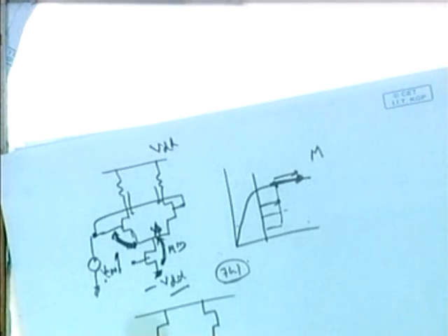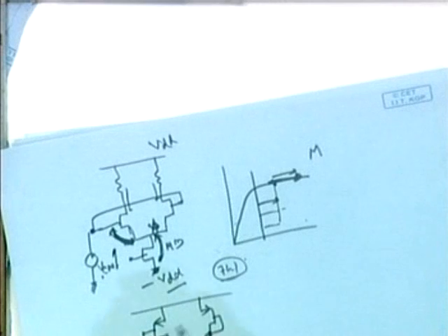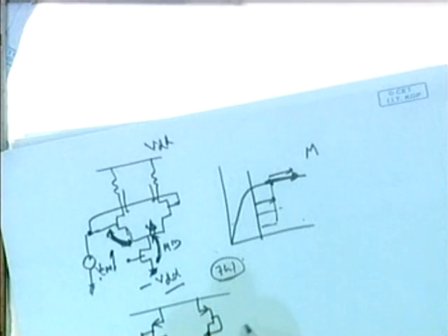This is a constant current source input. This is PMOS direct connected. These are all NMOS, these three are NMOS. So this is PMOS direct connected differential amplifier. And for NMOS, you have to invert those things in terminal and short accordingly. So if we take only one part of this, you will be having gain minus.